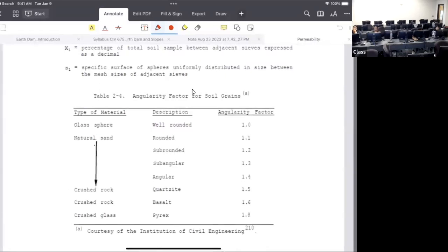Now, the other way of doing it is, let's say you have a rainfall, and after the rainfall, you look at the resistivity result. So do the first resistivity test, and then after a certain time, you do another resistivity test. Now, the only change between these two tests is your moisture content, right? So now if you set a certain target with a certain distance, you can predict the travel. It can be very useful.